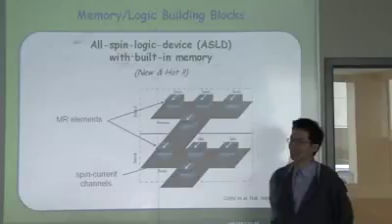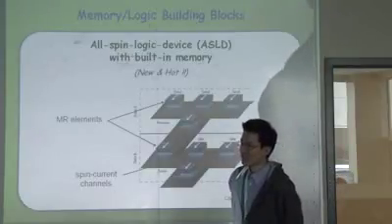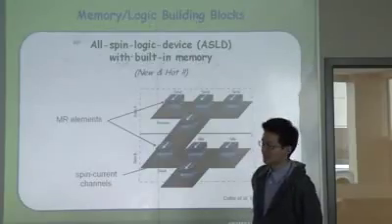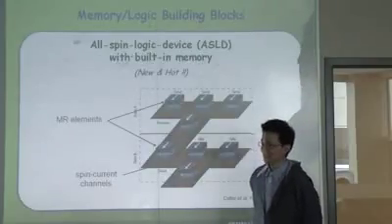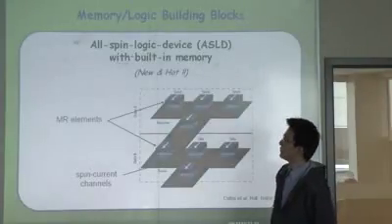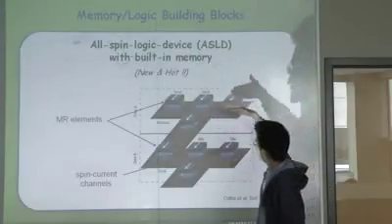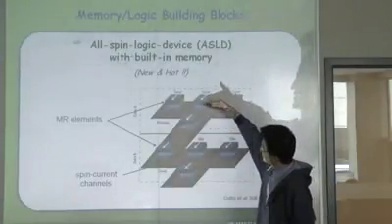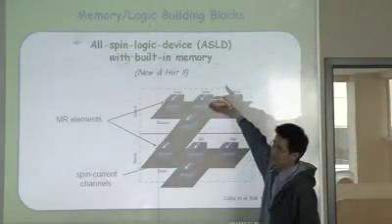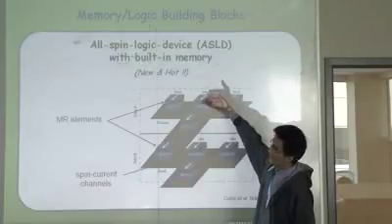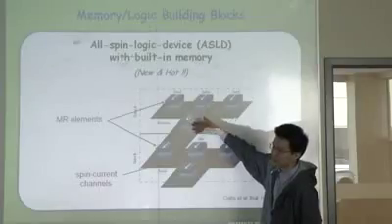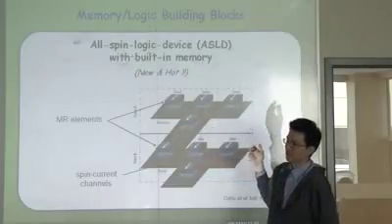Okay. Yeah, go ahead. How resistant to noise and decoherence is a spin polarized current over macroscopic distances? They can travel microns easily, but one thing built in here is that every signal only reaches this far. Beyond that, there's a blocker. So all you need is to propagate your spin information from here to here. You don't need to go beyond that. And this system will continue. It's sort of like the transistor performance.